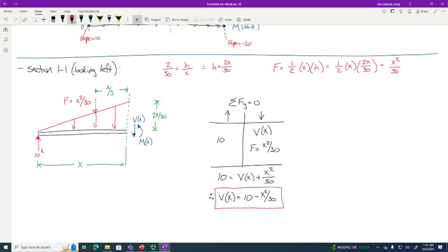Let's look at this equation real quick. If I were to graph that, what would it look like? I'm not asking for a perfect Calc 1 representation, but generally, what curve is this? A graph of a line? Parabola. It's a parabola. It's a quadratic. Didn't we say that for a linear load, the shear diagram should be quadratic? It's quadratic, right? Let's see what happens with moments.